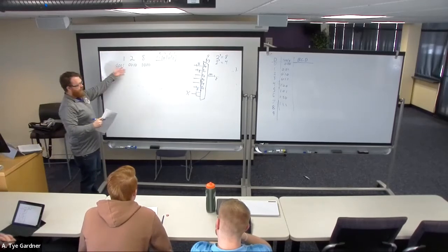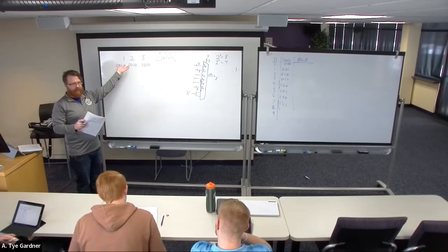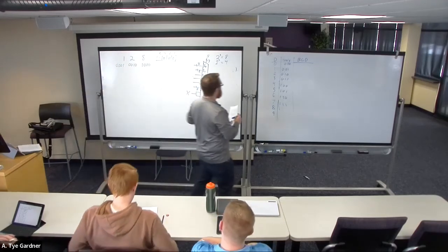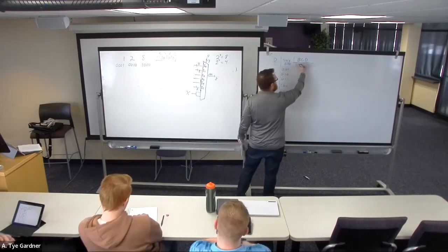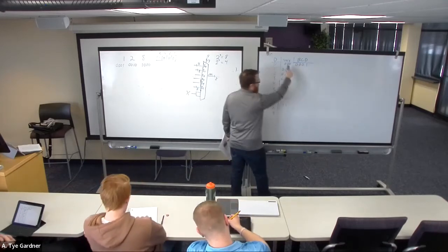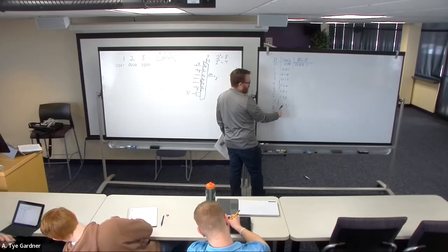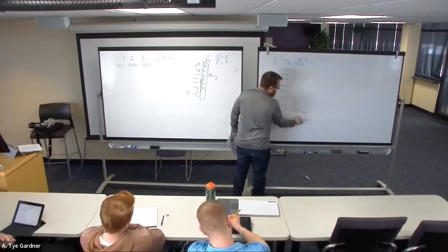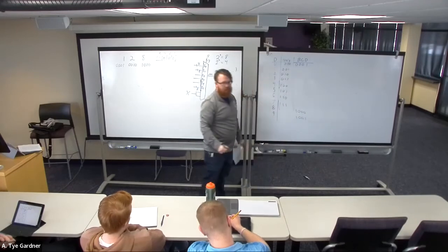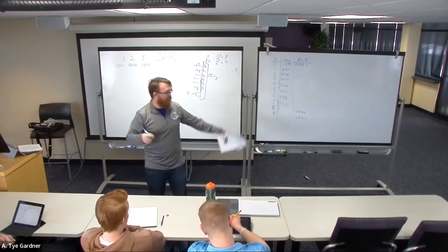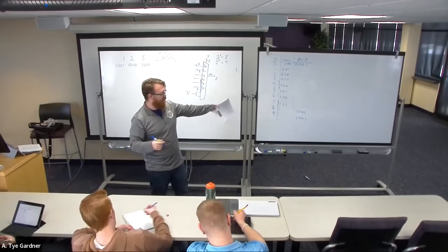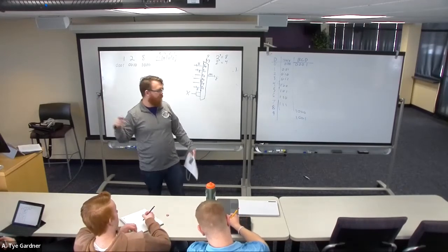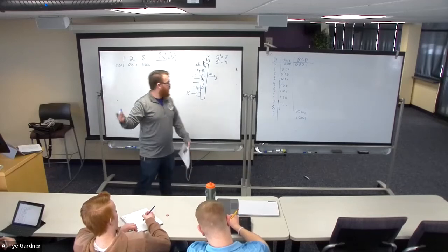If I were, say, designing a counter that wanted to display these, well, then I could come over here. It's the same thing, right? Here, it's the same as this column, which is the zeros, until you get down to 8, then it's 1, 0, 0, 0, 1, 0, 0, 1. The rest of those are thrown out. Sorry, the bottom rows for those that can't see is 1000, 1001, basically 1, 0, 0, 0, 1, 0, 0, 1. And that represents the 8 and 9.